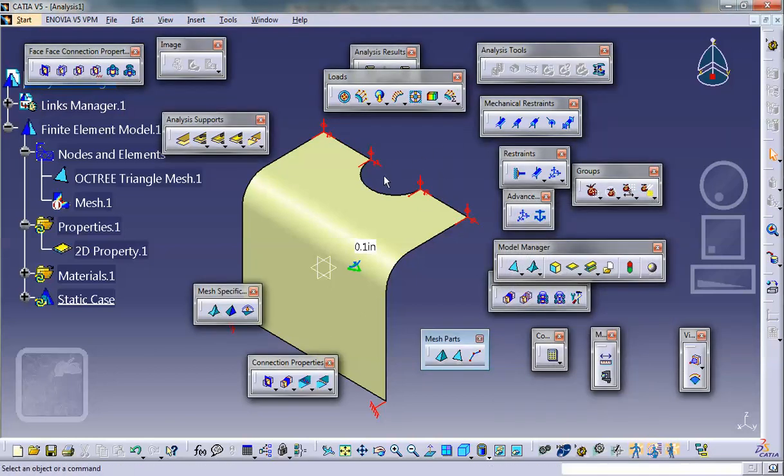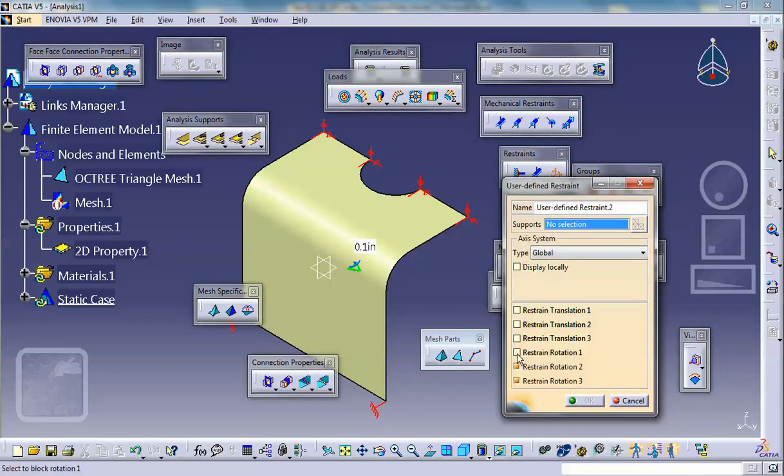All right. The entire circular arc is pushed in the Y direction. So in Catia, you know that in order to apply a non-zero displacement, first you give it a zero displacement and then you change it. So this circular edge, not the vertex, that entire edge.